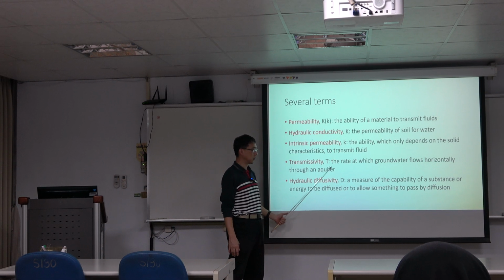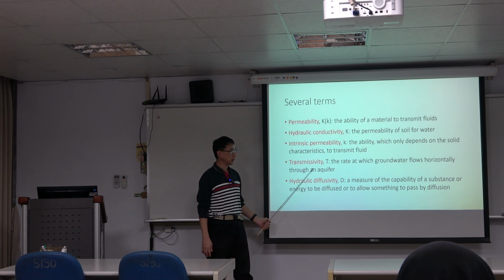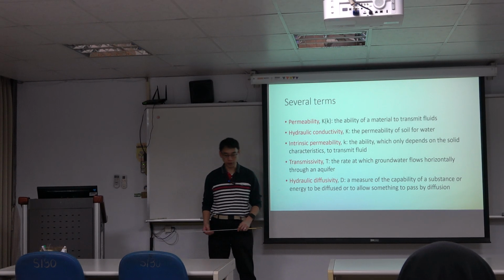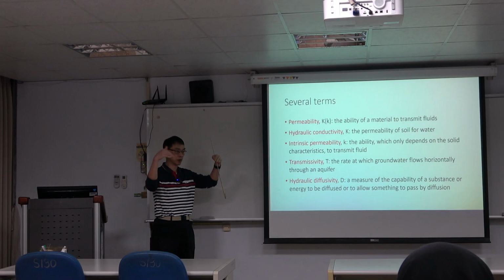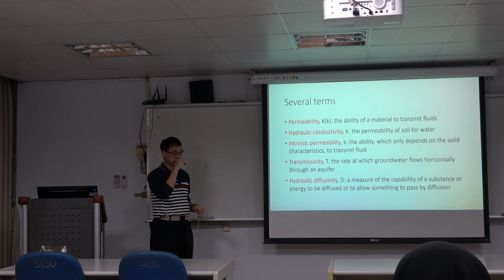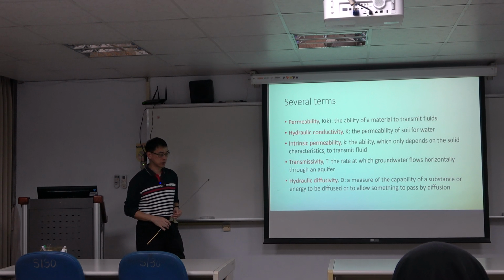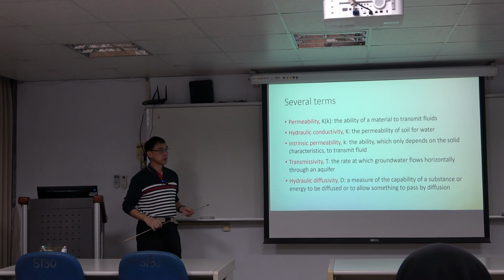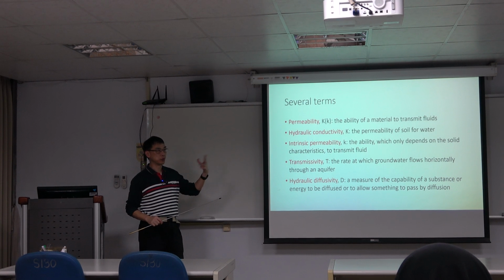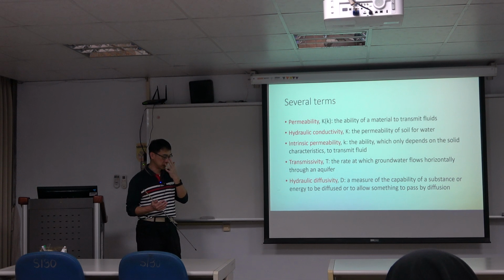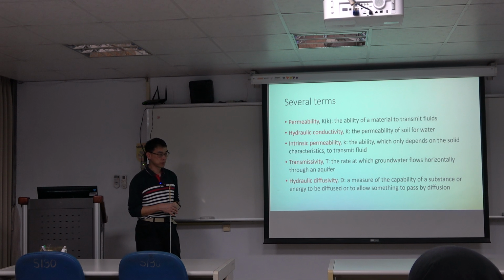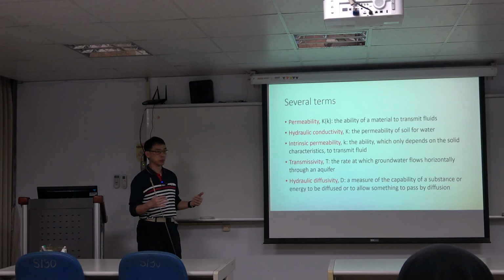So we mentioned the aquifer properties. And another, it emphasizes the horizontal movement, because when we're doing a pumping test, we assume that the water flows horizontally, without vertical components. Although it's also an ideal case. If we do the pumping test in real hydrogeological systems, as we saw in the last lectures, they are arbitrary materials or quite heterogeneous systems, so they are not able to have only horizontal movement.